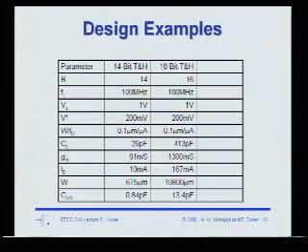So if your subthreshold swing is 2, then at 50 millivolts overdrive, you're at more or less the border of operating in weak inversion. So to operate in strong inversion, you want to be, let's say, a factor of 2 away from that, at least 100 millivolts. And if you want to be in moderate inversion, you're going to be somewhere in between.